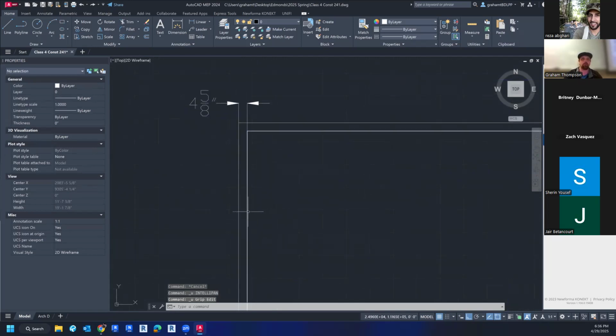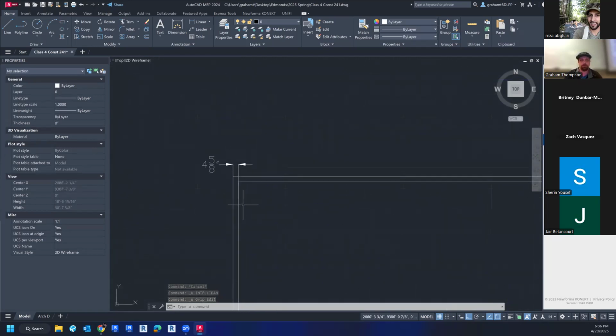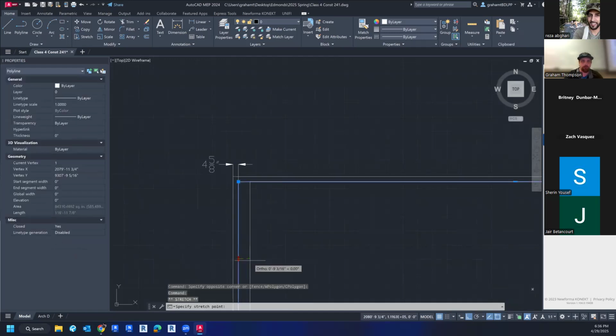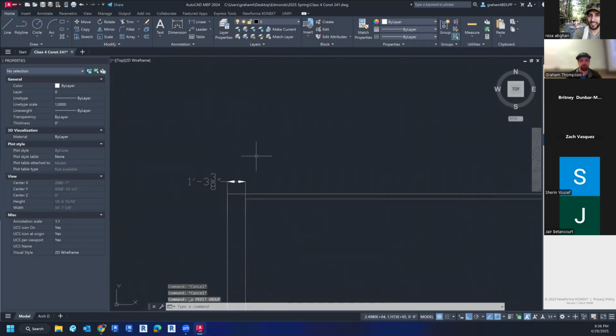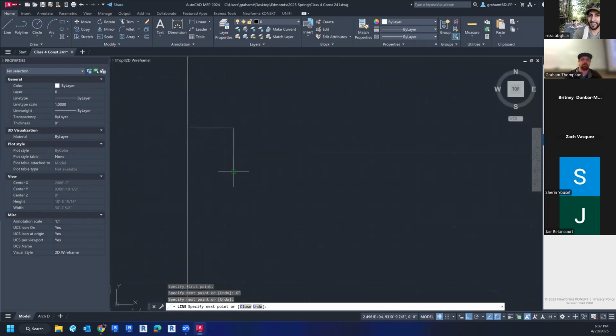Instead of playing this game where let's make this wall 6 inches, and I'm always constantly moving this in and out, let's back up a step and think about what we have learned. Sometimes you need to just make a line a certain length so you know where that location is. So I'm going to make a line up here. And now that I know that's there, I can make a line off of that, 6 inches over. And then I'll make a line straight down.